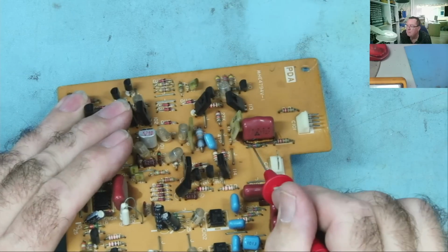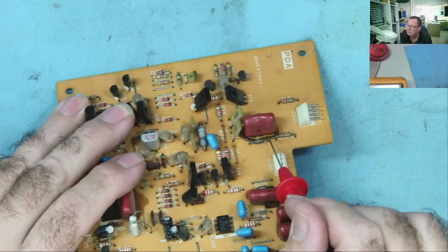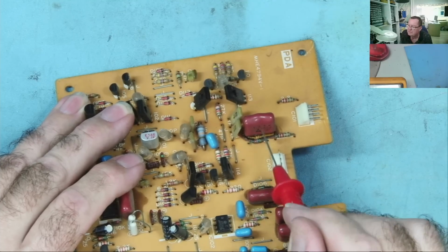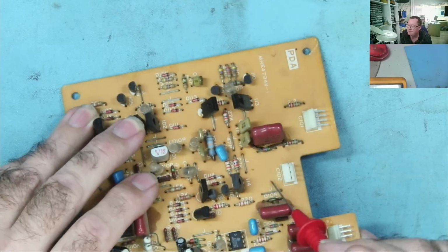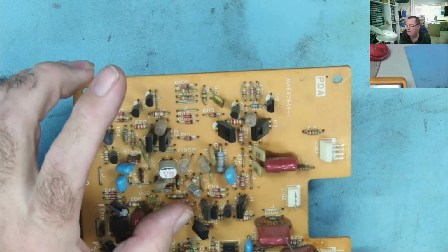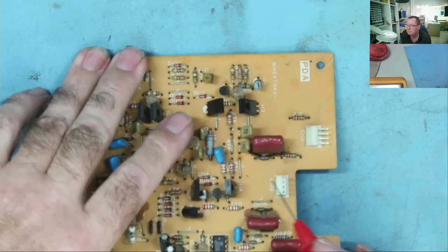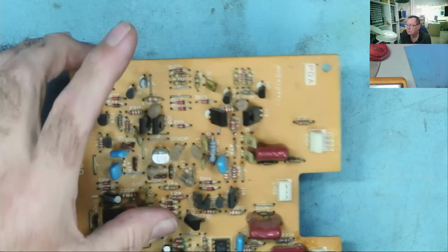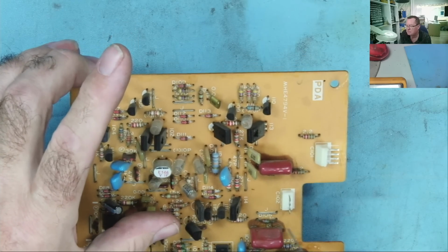This looks like it might be the problem actually. You see this horrible glue stuff here? I wonder if that's gone conductive. That's the diode, that's the capacitor. This is J, so we can lift J. I mean, we have a similar thing here, but it's not quite as dark as that one. But if that's caused a problem, this probably will as well, unless I remove that.